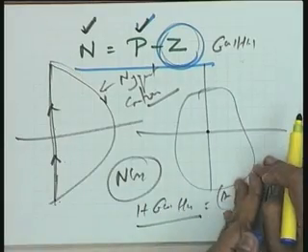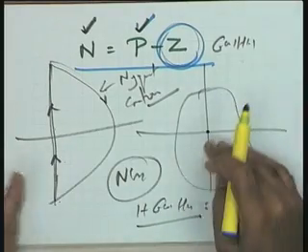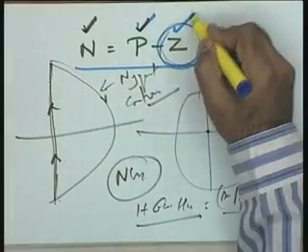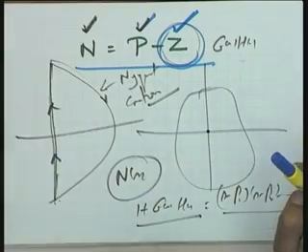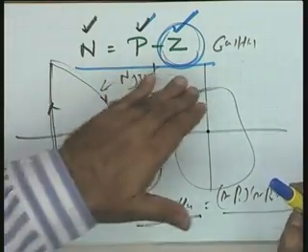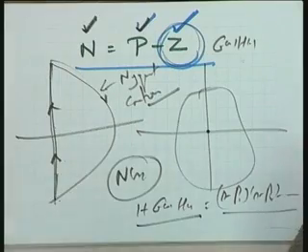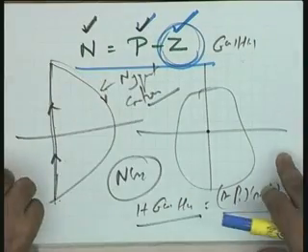It gives you information on the number of zeros of 1 plus GSHS in the right half plane, which is equivalent to the number of closed loop poles in the right half plane. So it means the procedure is this, that you take this contour, map it, and see the number of encirclements of the origin and apply this particular algorithm to check whether the system is stable or not. If it is unstable, how many closed loop poles lie in the right half plane. Okay. If this is clear, then help me please equivalently.